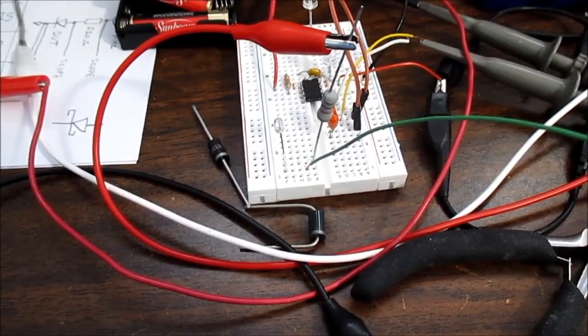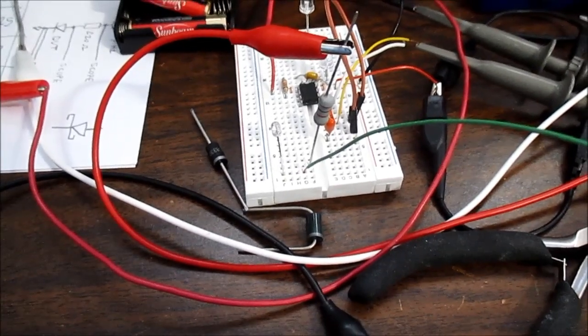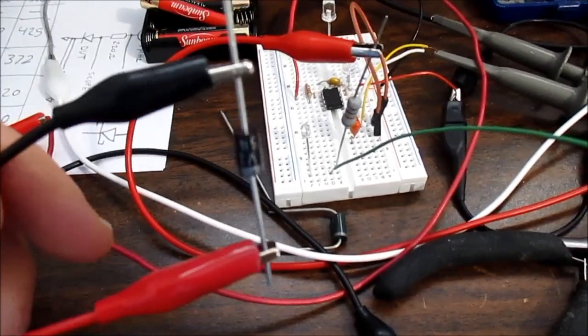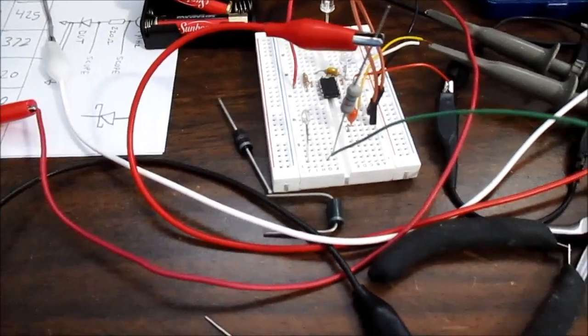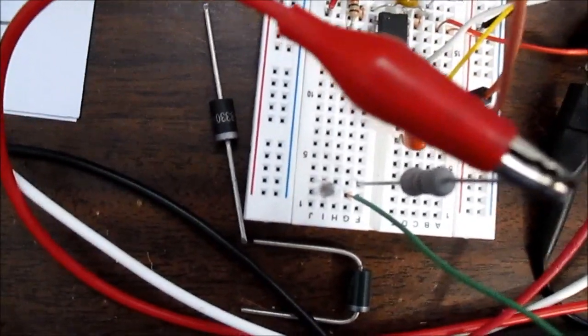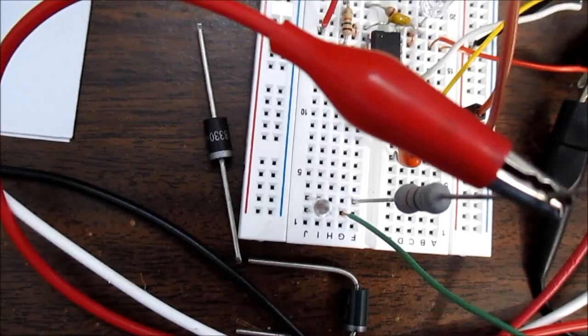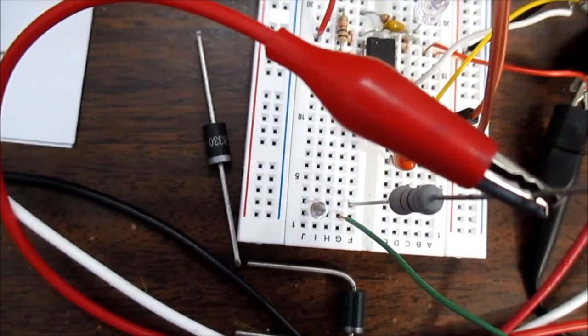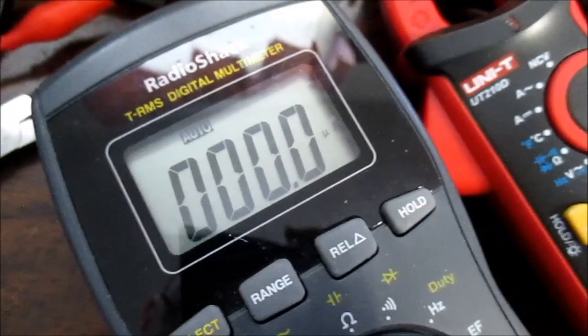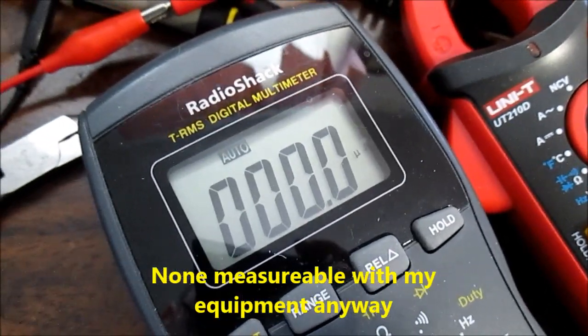So now I'm doing a reverse bias leak test to see how much current these leak. First, we'll start with the 1N5404, and I'm passing the current through a green LED. Apologies, I do have to hand hold the camera, but nothing, no leakage at all.